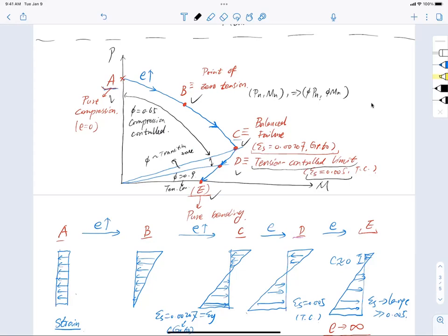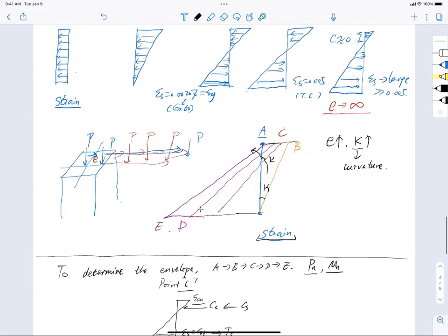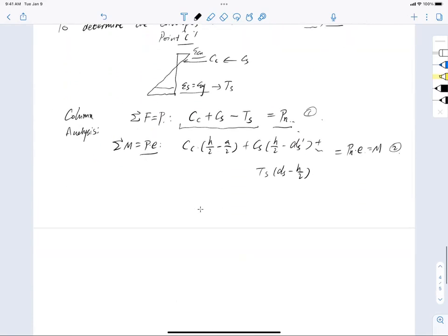All right. Once you figure out the Pn and Mn, throughout the process you will use the corresponding phi to find your design moment. So we say that as our eccentricity changes, the stress state in the column changes, and correspondingly the moment and axial loading change as well.